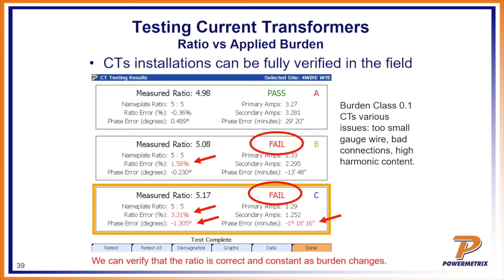In our area, we're governed by TVA, which is Tennessee Valley Authority, and they give the utility 2% plus or minus total error. And so our customers around this area set up their Powermaster to be within plus or minus 2%. So if it fails outside that number, this number goes red. In this case, I think this one was set up as a 1% error. So that's why these things pop up and fail. But we're at least validating that the ratio is coming out as expected.